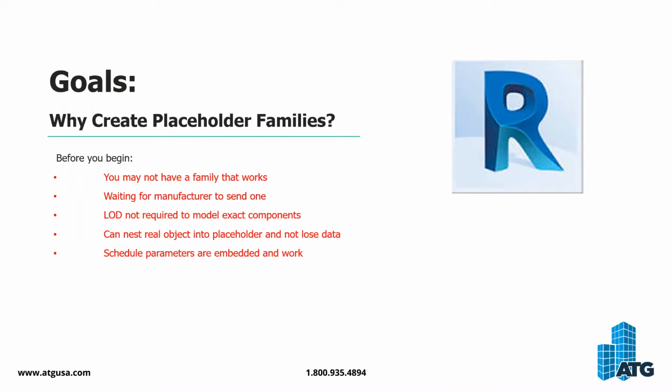Because if you go to Lithonia or Daylight, sometimes you have the options for hundreds, if not thousands, of families to download. And the only real benefit in most of those is you'd get their IES files as well embedded in their direct family. But if they don't schedule, you can spend a lot more time adding those shared parameters into their families to make them work for you than you would just re-embedding the new IES file in your placeholder family in that case. So, things to consider when you're talking about placeholder families.